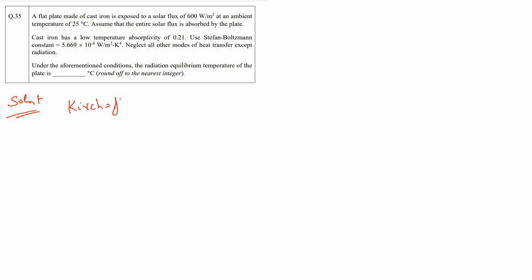You might have heard of Kirchhoff's law in basic electrical topics, but this is a little bit different. It states that the total hemispherical emissivity of a surface at temperature T is equal to the absorptivity for the radiation coming from a black body at the same temperature.